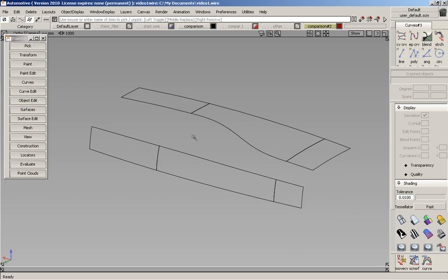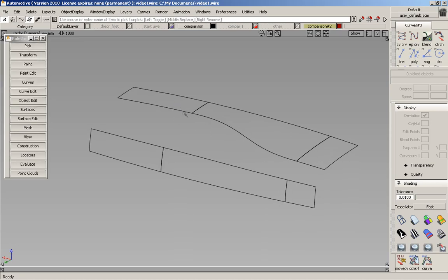And let's say you want a fillet boundary or a blend that looks like this example, where you have a large fillet that tapers down to a small fillet. But it's not a complete variable radius where it's equal on both sides. The top has more of a stylized line to it, or a stylized boundary. So traditionally, I can use the Freeform Blend or the Surface Fillet to build this blend.